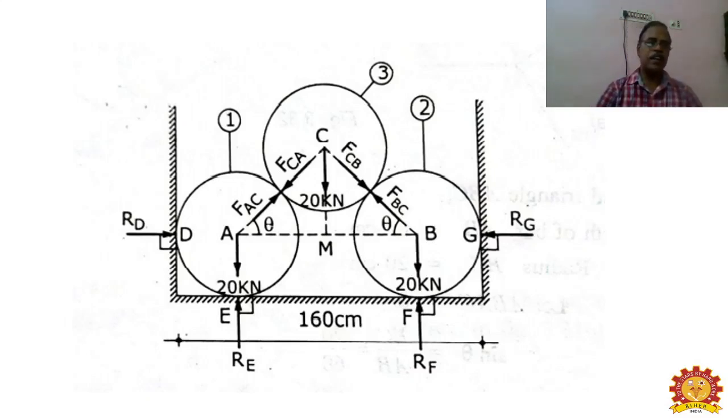That's the solution you have to write at the end. Before that, since there are 3 forces, you have to take the free body diagram for cylinder 3 and get the solution, and then go for the free body diagram for cylinder 1, find all these forces and get the solution. Resolving these two cylinders is more than sufficient to find the answer.